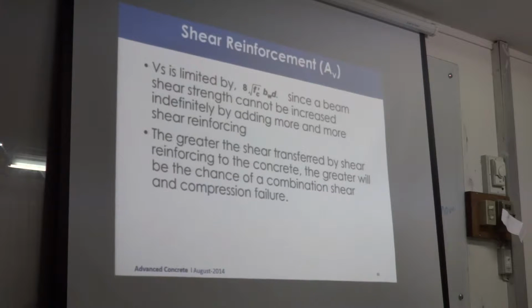However, if the concrete capacity in shear is 10 and your shear is 8, you are still less than concrete capacity, but code will ask you to put some minimum reinforcement here, just in case. Right? Just in case the concrete cracks, you still have some reinforcement. If your shear is more than 10, let's say it's 13, then you have to provide reinforcement for 3. 10 will be taken by concrete, 3 will be provided by steel. And suppose the maximum concrete capacity to carry shear is 20. You are between 10 and 20. You can calculate the difference between your shear minus 10 and the remaining goes to the steel. If you are more than 20, stop. Right? So basically we have these 4 zones of shear design. Clear? Okay.